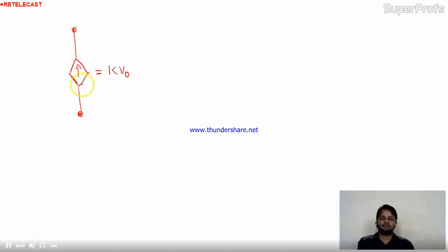This source is the current source. Why current source? Because of the arrow inside the diamond. So this is definitely the value of some current. But the current depends on which parameter of the circuit? Voltage, right? So is this current controlled by voltage or current? Yes, absolutely, this I is controlled by a voltage value.